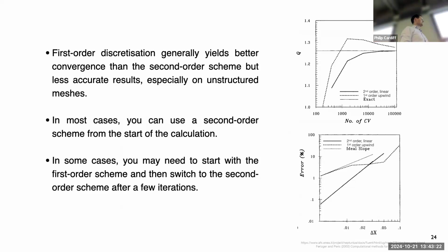So you have to be very careful if you use first order upwind. So why does it exist, if I'm making it sound so terrible? Sometimes if you start with second order schemes in a CFD problem, from the start, everything just blows up. So what people often use is they'll start with first order schemes, highly diffusive first order upwind. You'll get an initial flow field and it's stable. And then you stop the calculation, switch to the higher order schemes and restart. So if you have a good guess, the second order schemes won't explode. So the idea is you start with the lower order schemes.